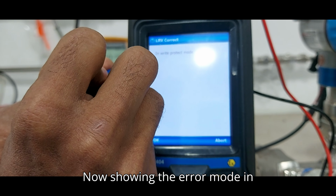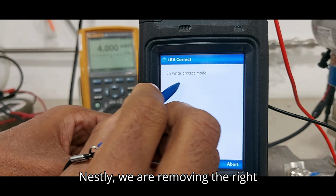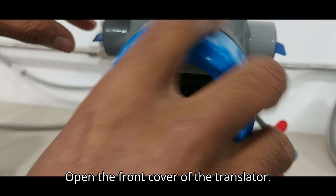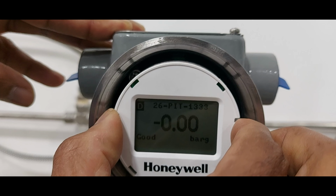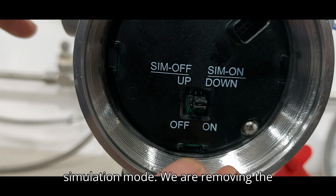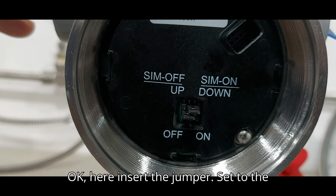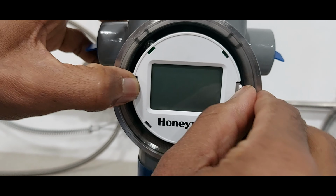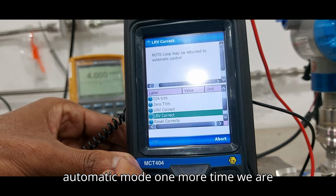Now it is showing the error mode, the write protection mode. Next we are removing the write protection mode in the transmitter. Open the front cover of the transmitter. Remove the display. Downside is security mode, upside is simulation mode. We are setting the security mode to the off condition. Here insert the jumper, insert the display. Then press OK. Return to automatic mode.